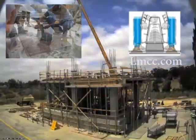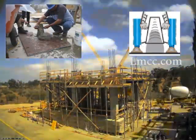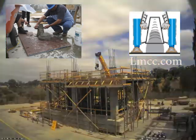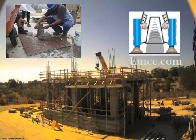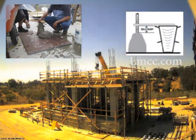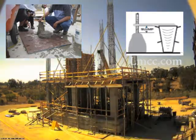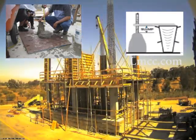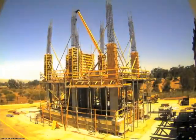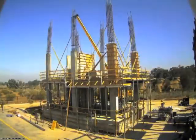The mould is then removed slowly and placed adjacent to the concrete specimen. The free concrete is allowed to slump down under its own gravitational weight. After the slump settles, the metal rod is levelled horizontally on top of the mould, and the distance from the horizontal rod to the top of the concrete is measured. The change in height of the concrete sample is referred to as the slump for that specific batch of mix. The slump measurement is compared with specified values, and a decision is made on the spot whether to accept or reject the concrete mix before placing the concrete.